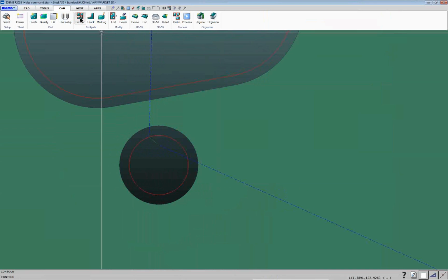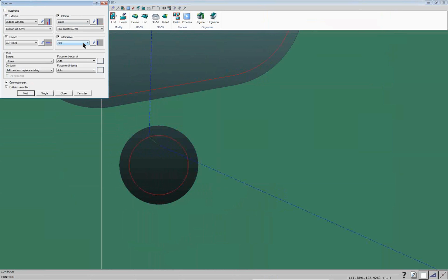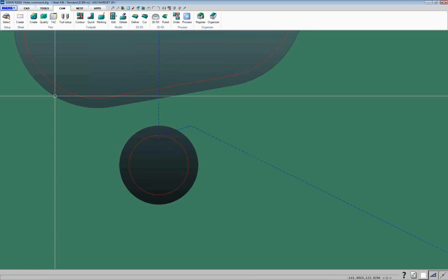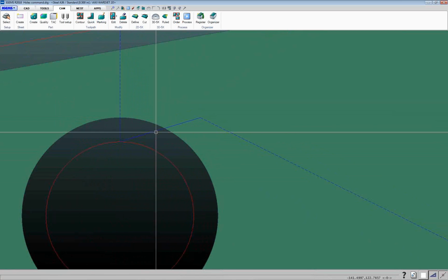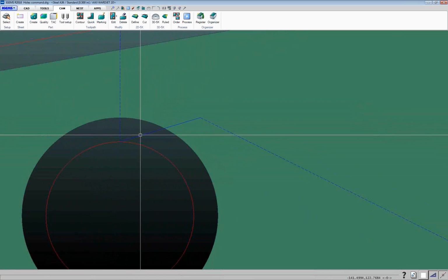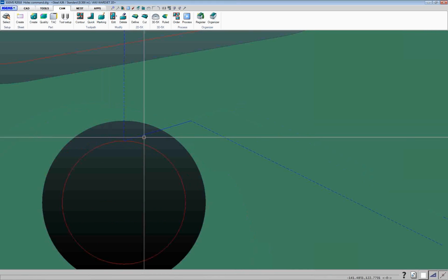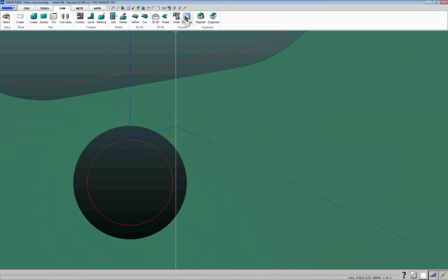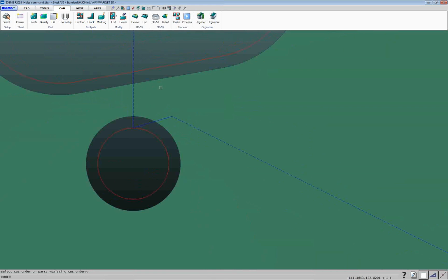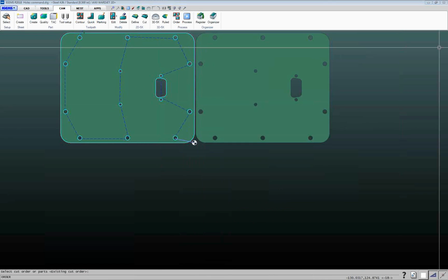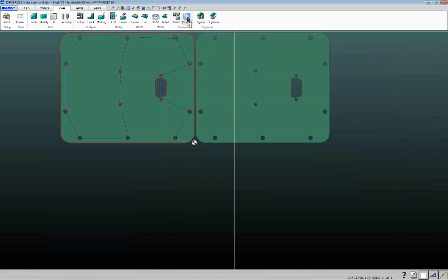The other option there is the blind lead. So if I switch this to blind, and I'll put the leads back on here again. So now you can see that little green lead-in line has now been replaced by this solid blue rapid line here. And this is there because we need to make a very short move in order to apply our tool offset to a cut.